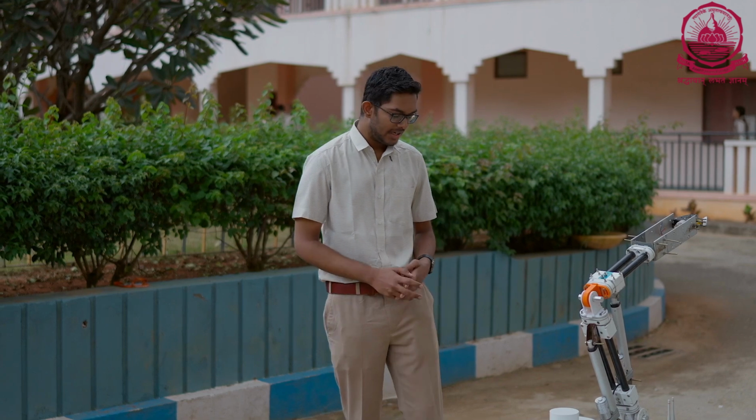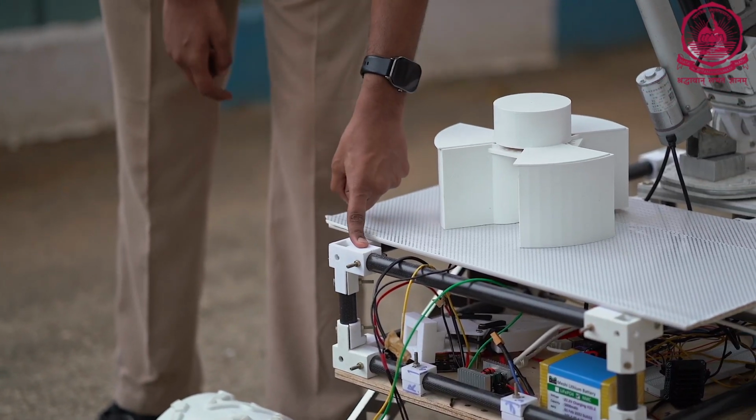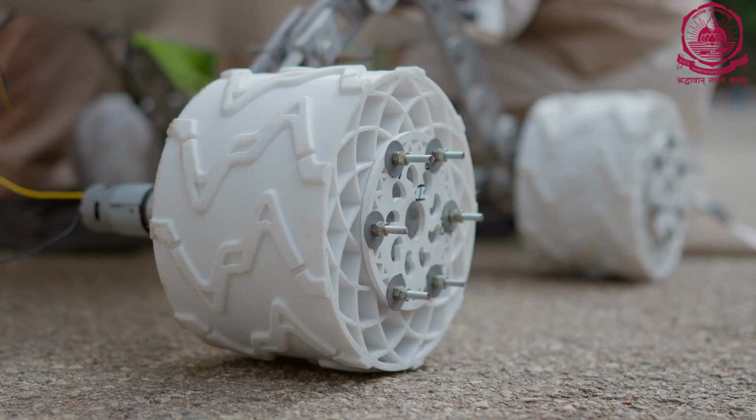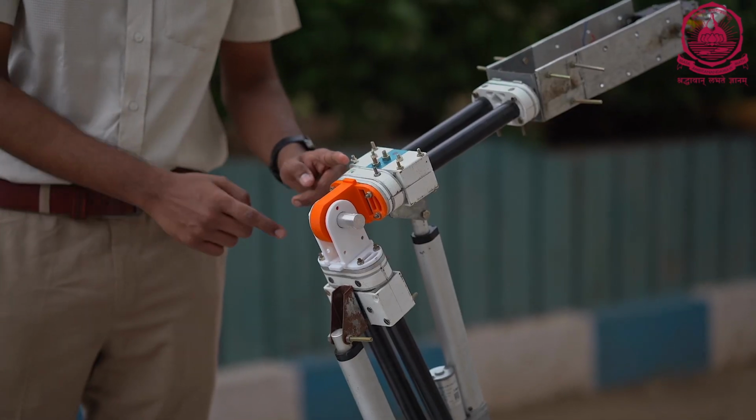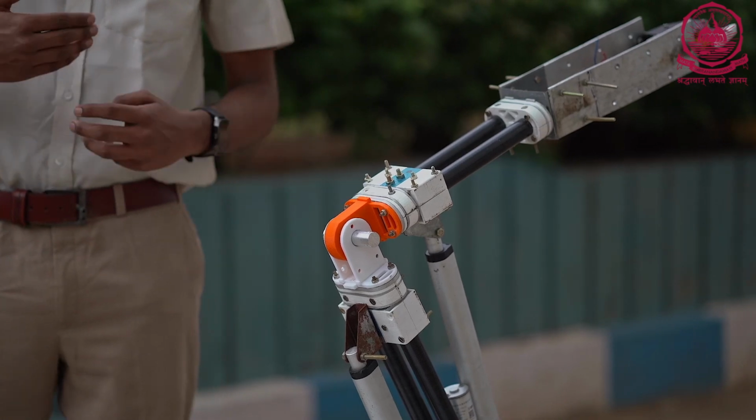Hello, we are from the mechanical subsystem. We design and build the rover. The rover is built with carbon fiber rods and 3D printed tough PLA and TPU materials for the joints and the wheels. We also used metal parts sandwiched between 2 3D printed parts to provide additional strength while also keeping the system light in weight.